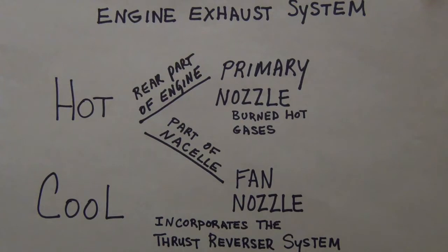All right. And then also just keep in mind, your centralized fault display system, your CFDS, is interfacing with the EIU, your engine interface unit. And that's going to be providing fault diagnostics for the thrust reverse system. So it's monitoring, it's checking, and if there's a fault, that becomes known, and then what? If it's not repairable quickly, then you'd have to actually deactivate and lock out that thrust reverse system.